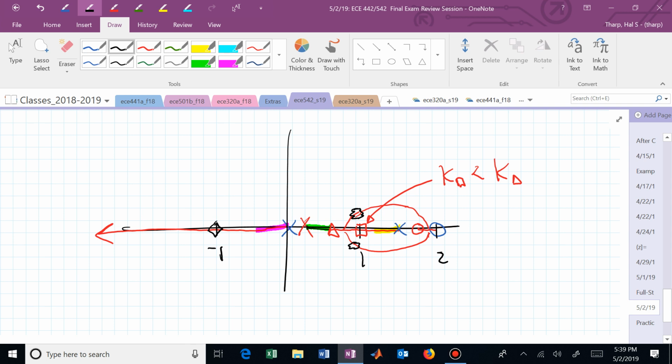Can we determine the position of the cloud? Can we? The answer is a qualified yes. On the final, maybe not. But you can. How would you verify if cloud is on the root locus? You just told me phase angle condition. You could say, well, I think this is about the place where, but you know that those curved lines are not necessarily circular, right? Because that's not 2 poles and a 0. This is now 3 poles and 2 zeros. All bets are off. Yes?